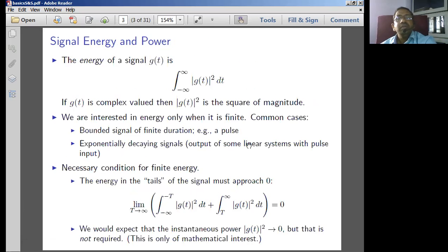And for signals, we have another variety, energy and power. They are not in the syllabus, but still they are very primitive and basic representations of a signal. Energy of a signal can be represented like this: if I have a voltage signal, what is its energy? I simply say integral of v square dt. If v depends on time, I write integral of v of t square dt. So I find the modulus value. If any complex components are inside this function, they are simply converted into a real value.